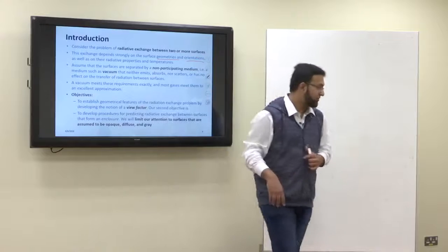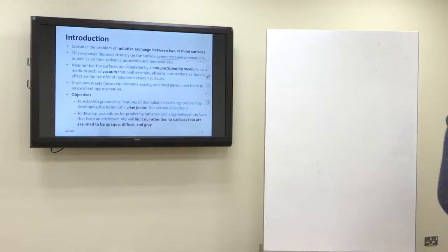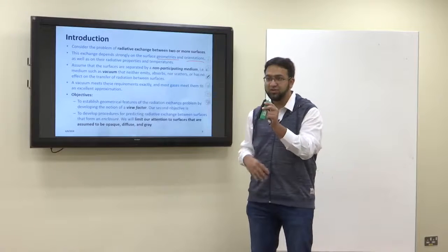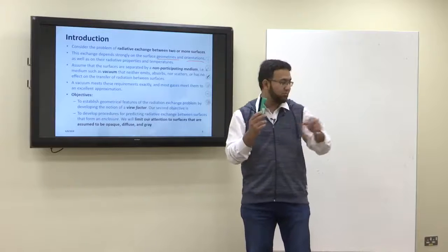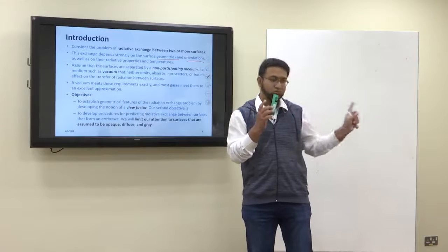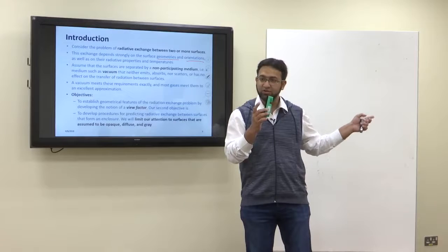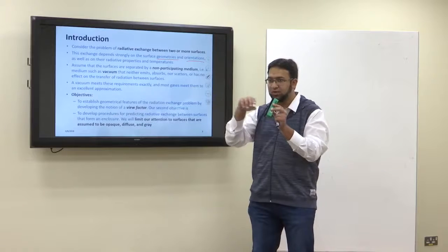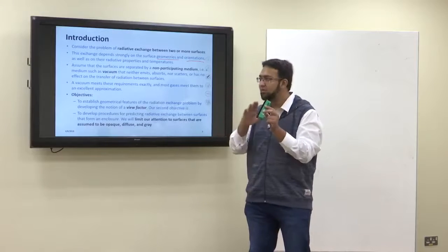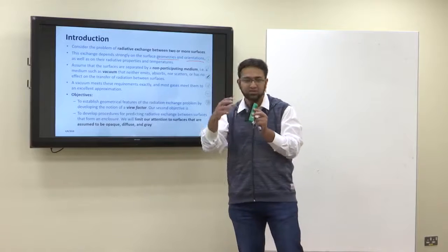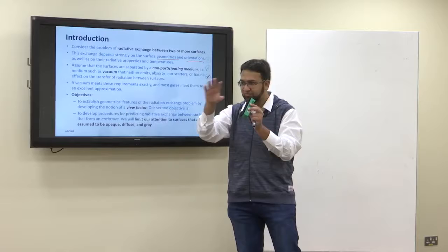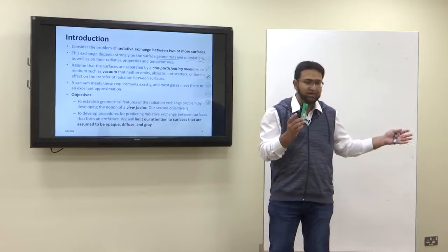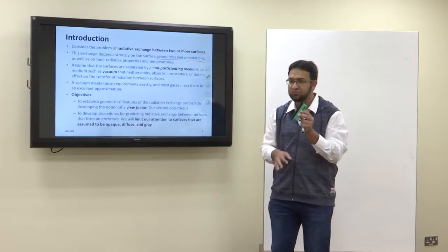Okay, so if this is my body, and suppose the radiations emitted from this surface are in this direction, then none of the radiation will be transferred from this surface to anything which is behind the body, because radiations move in straight directions. Okay, they do not get curved, they move in a straight path, and it's a hemispherical emission. So the view of anything behind it is not there for this surface.